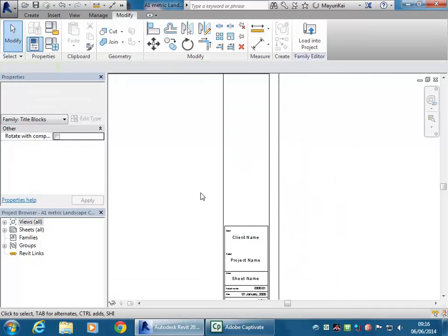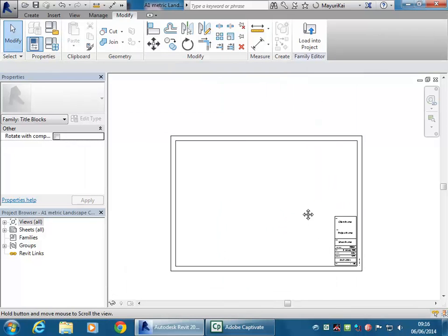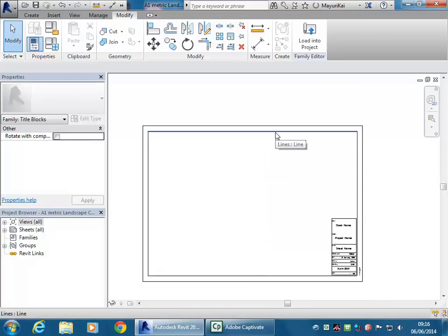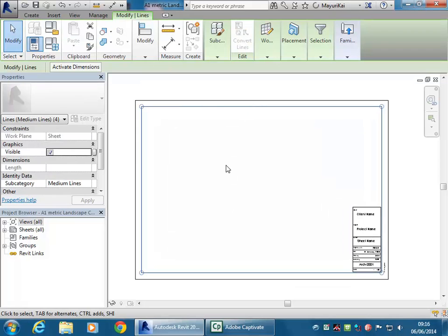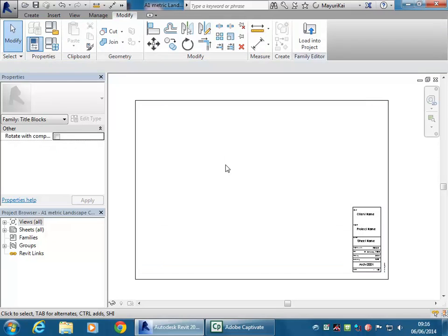Right, so I might take this last couple of lines off, and you don't really even need to keep the border on the inside. The outer border you need to keep because that sets the frame for the page. But if you like, you can get rid of that inner border, because otherwise that will print. So the outer border is the edge of the page? Exactly, yeah. And when you're printing, does that mean that the print border is actually that border that you created? No, that's a frame within that. So it actually is an edge that would print otherwise.